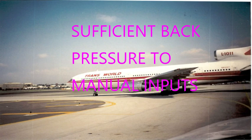Basically, you're manipulating a fine balance with the right amount of speed, the pitch, your angle of attack, in order to safely clear the tail of the plane from the ground. There have been incidents and accidents where the pilot input was not quite right and there was a tail strike. So that has happened.